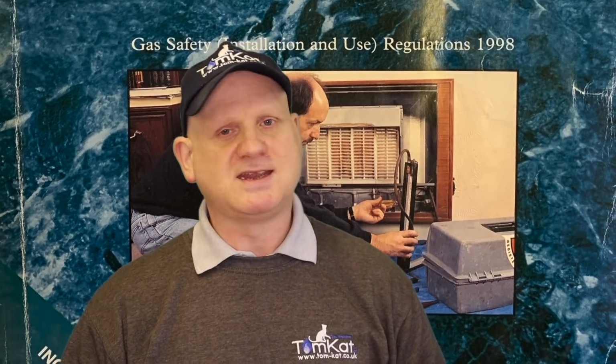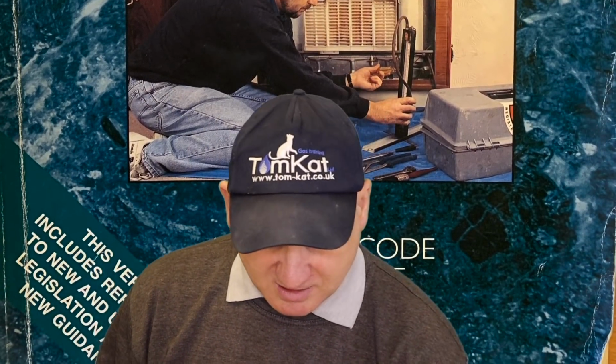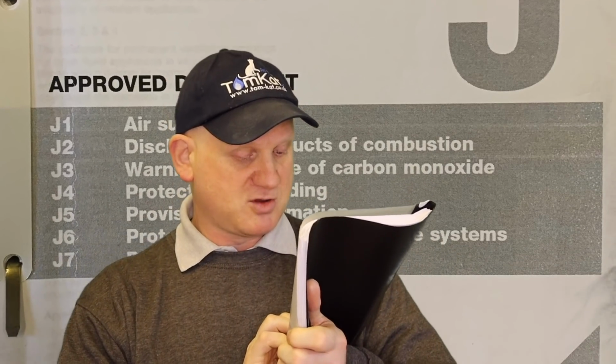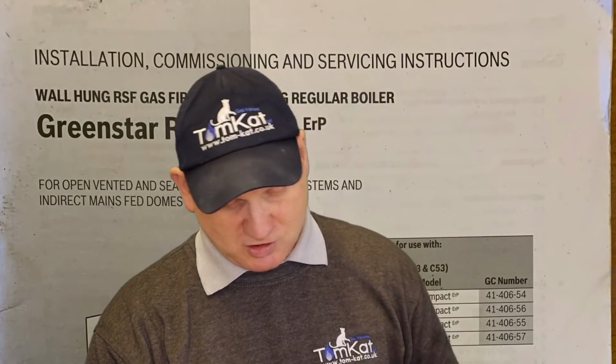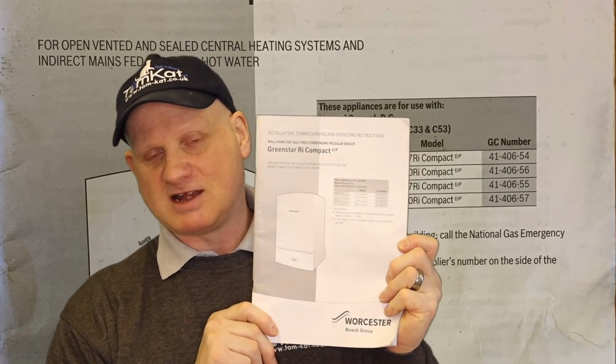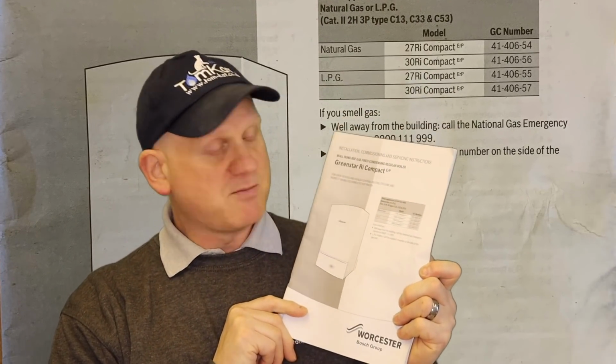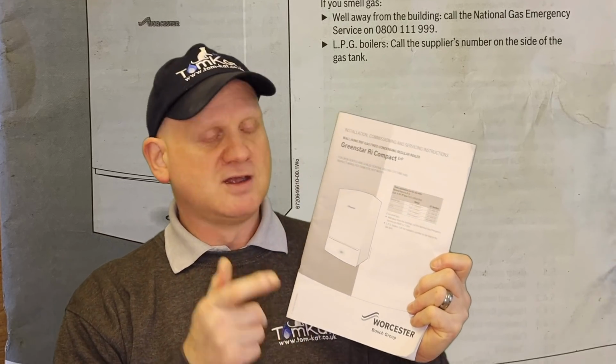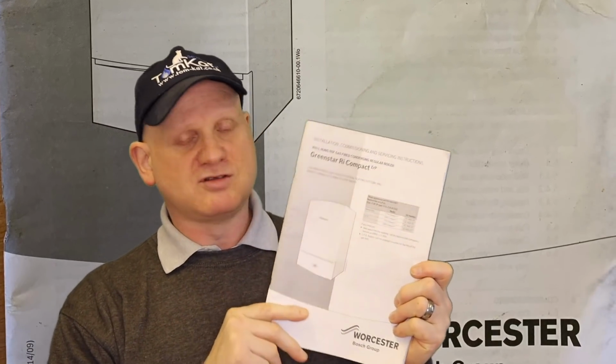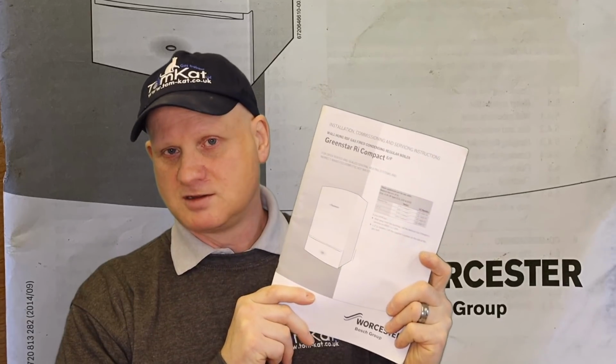We've also got the Gas Safety Installation and Use Regulations 1998, which was amended in 2018. We've also got Building Regulations Document J, which is the approved document for air supply, discharge of products of combustion. So Document J. And of course, we'll always need the manufacturer's instructions for any boilers or any gas appliance, because we go off the manufacturer's instructions for when we're looking at flues.